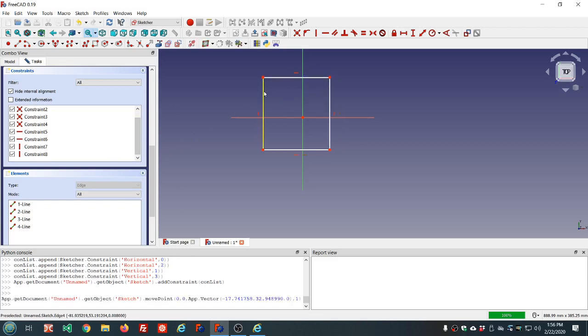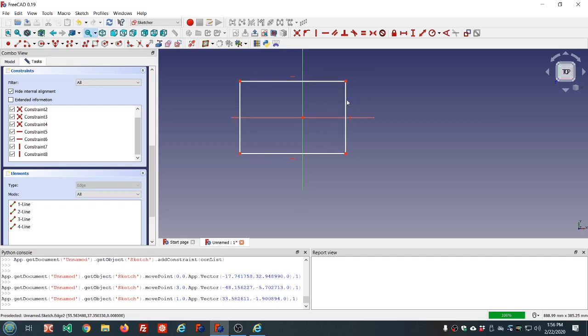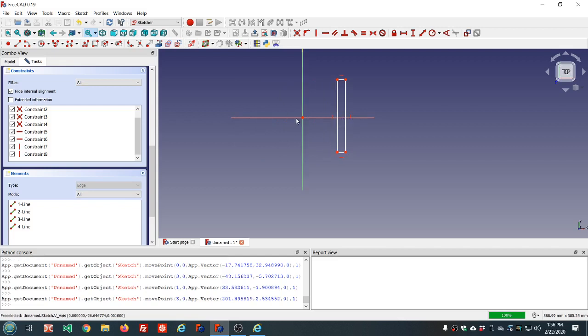Often we like to center our sketch. Unless there's a reason not to, you should always center it. When I made the funnel sketch, I did not center because I wanted to rotate about the z-axis, which is the y-axis here, but it was on the xz plane, and I wanted it out over here so I could set the radius with this distance. But ordinarily I would want to center my sketch.